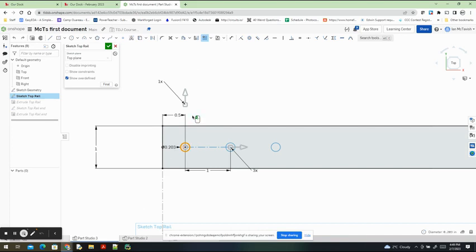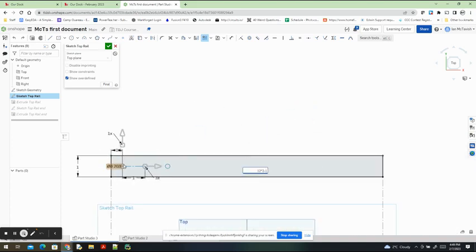Now, the default is that it repeats once upwards and 3 times to the right. So we don't want any upwards, so that's fine. That's perfect. This way, though, we want more than 3. So our item is 12 inches. Now we want it every 1/2 inch, so times 2. And we'll subtract 1, because we're already 1/2 an inch out. If we did 12 times 2, which is 24, that last one would be halfway on this line. So we're just going to subtract 1, and hit enter.